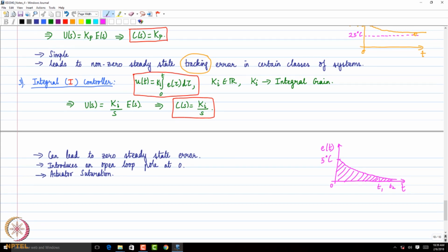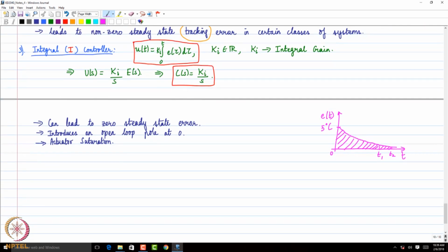Because I may say settling time would be so much with 1000 newtons, and peak overshoot would be lower than, let's say, 5% if you give 1000 newtons, but the capacity of the actuator is only 100. So in theory, while designing, I can put in whatever value I want, but we need to be realistic as far as maintaining the control input within the actuator range is concerned. So that's something we will also look at when we do integral control.